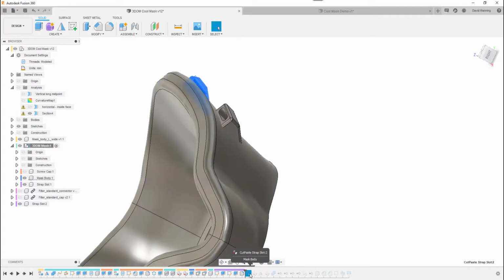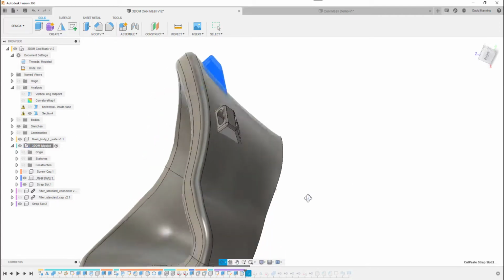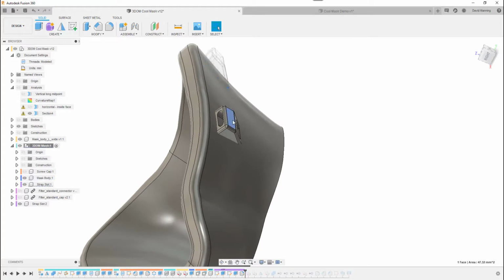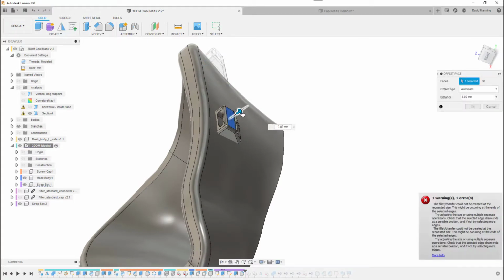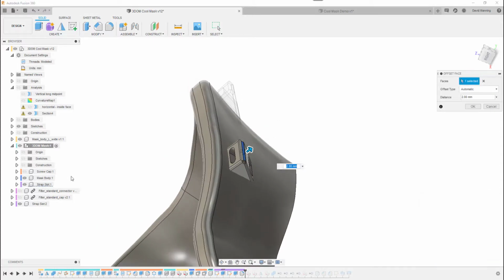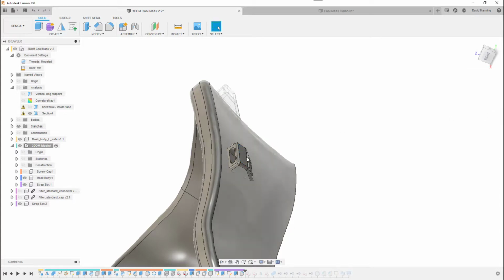That is simply to duplicate that component. Now let's just test whether I did paste or paste new. If I offset that, you'll see that does both components. You can see it over there. That means that I've done paste, which means they are linked together. Cancelling that, which is great because it means I can go back and edit this original component, and it will do that.